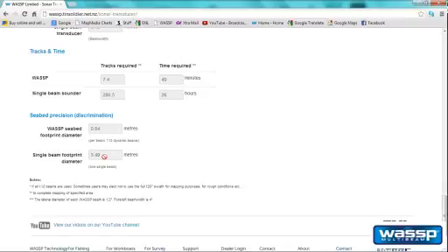So here's the secret as to why we can draw those nooks and crannies, because there's a hell of a lot of averaging going on in this 3.49 meter beam width. You can imagine any nooks or crannies that are narrower than 3.49 meters, you're simply not going to see into them. So it's going to draw the seabed as not having any hole where there really is a hole smaller than 3.49 meters. And additionally, if you are near to the rock but not actually on it, if any part of your beam is touching that rock, it's going to say that you're on it. So there's an element of misinformation because this data is not very accurate.